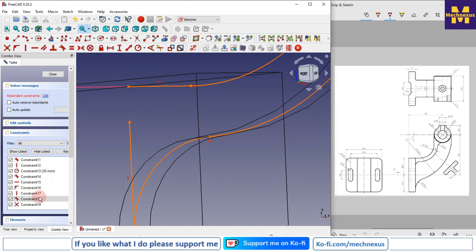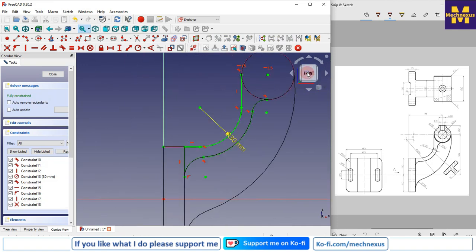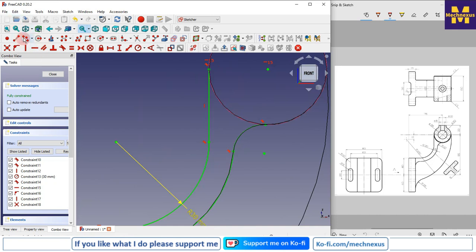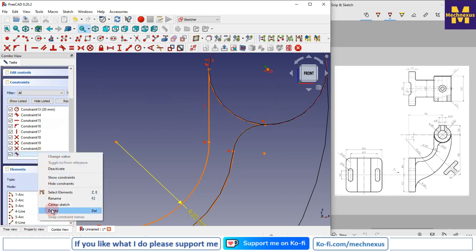So here is some problem, will delete it, and I will also close this one. So a very simple trick is I will select a 3-point arc, and you can see when you make it closer to the circumference it shows the tangency. Now if you move here it will not show, but if you make it closer, just drop it and delete the conflict.